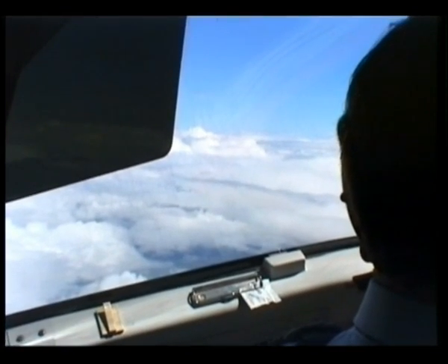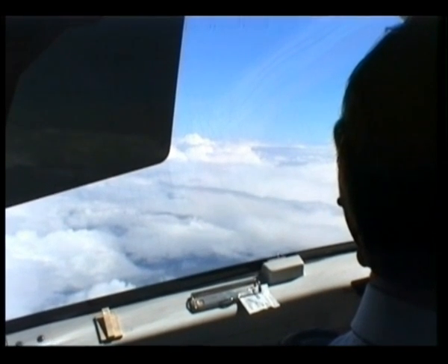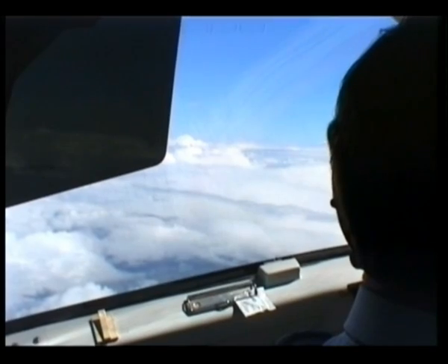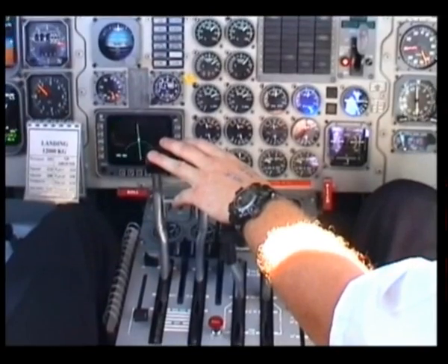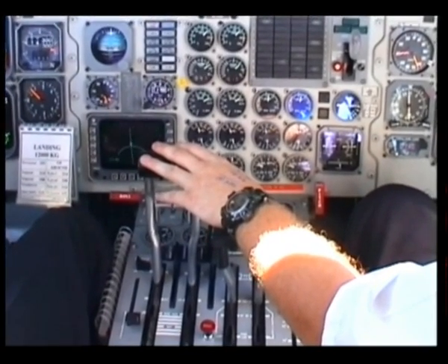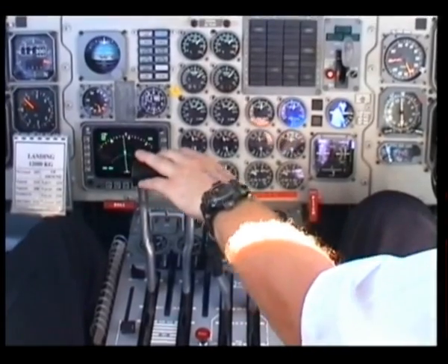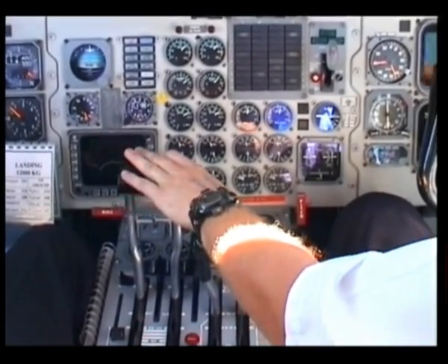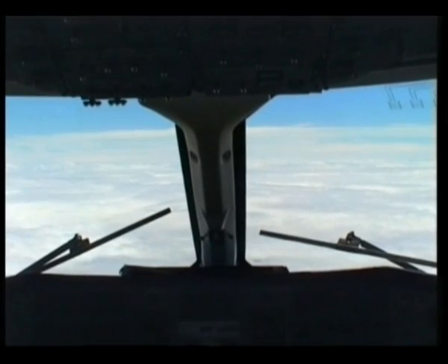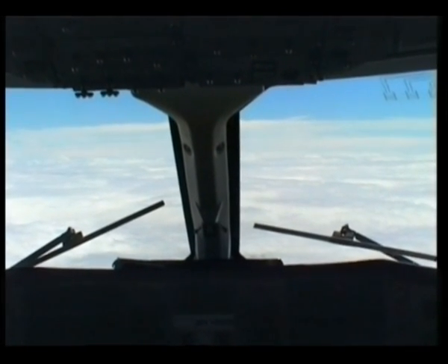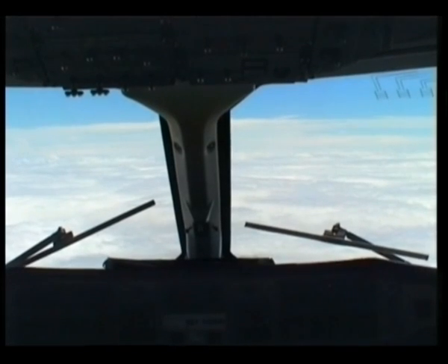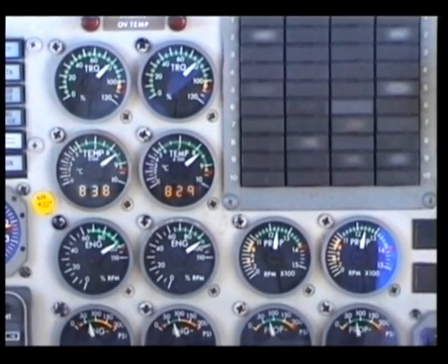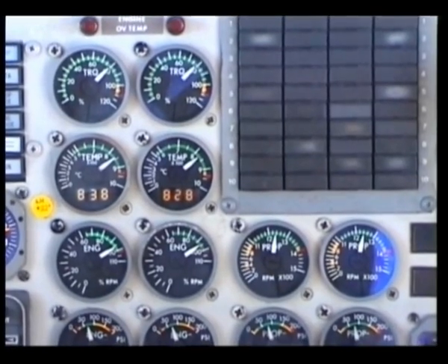An aircraft's weight decreases as it burns off fuel. As the wings do not change size, the wing loading decreases. If the aircraft remained at the same altitude so that the air density remained constant, the decreasing wing load would require the aircraft to slow down, and the efficiency of the gas turbine engine would suffer, as they do not perform optimally at lower RPMs. And so, as its weight decreases, the aircraft must find more rarefied air in order to maintain speed.